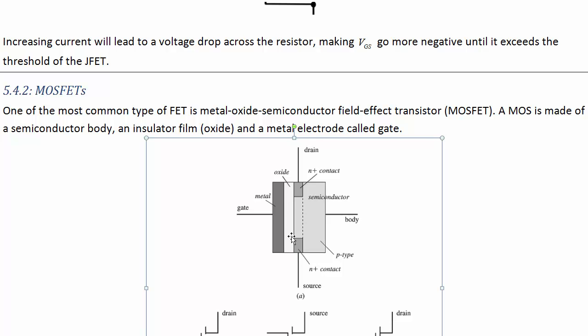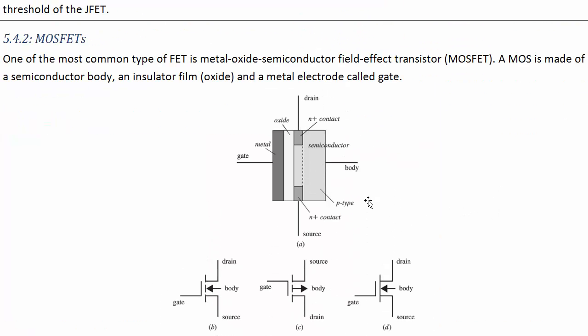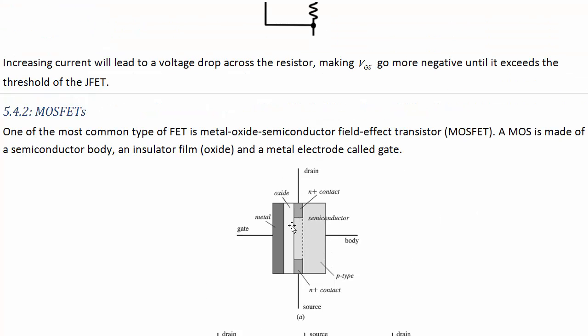Anyway, the oxide is quite thin, so in new devices, sub 20 nanometers. Now, if you're watching this in the future, then feel free to laugh at how quaint the thinness of our oxides today are once you've got your 1 nanometer quantum computer oxides. Anyway, so the oxide in a FET is quite thin, and still no current flows through there in DC.